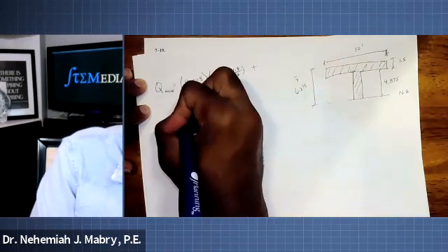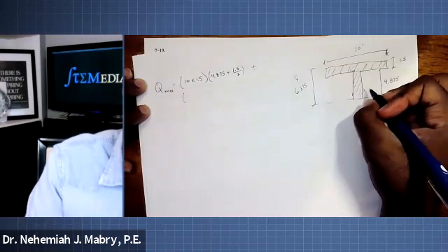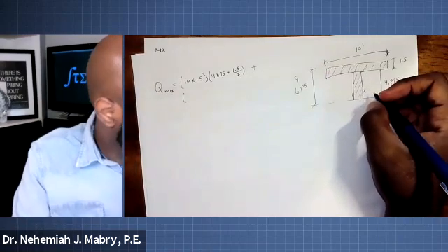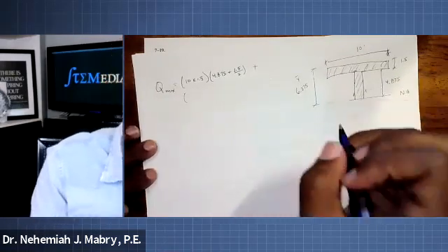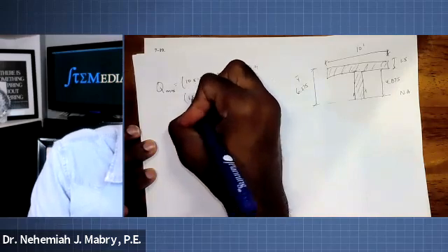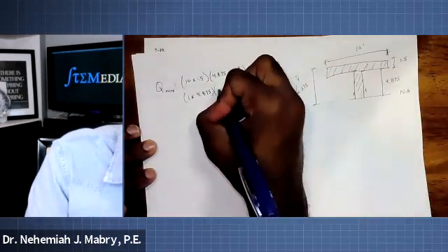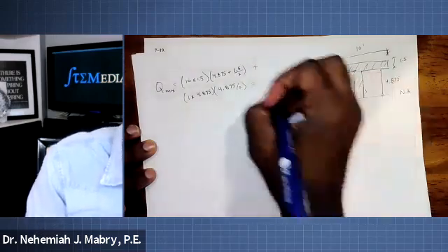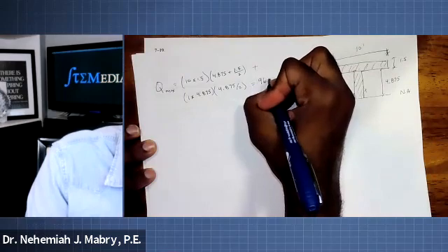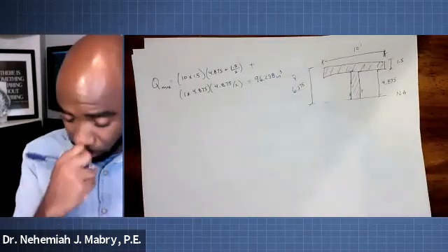Now we add that to the Q for the bottom part. We know the width of this, according to our diagram, is 1 inch. So 1 times 4.875 times simply half of 4.875. And from there, we can get that Q max is 96.258 inches to the third.